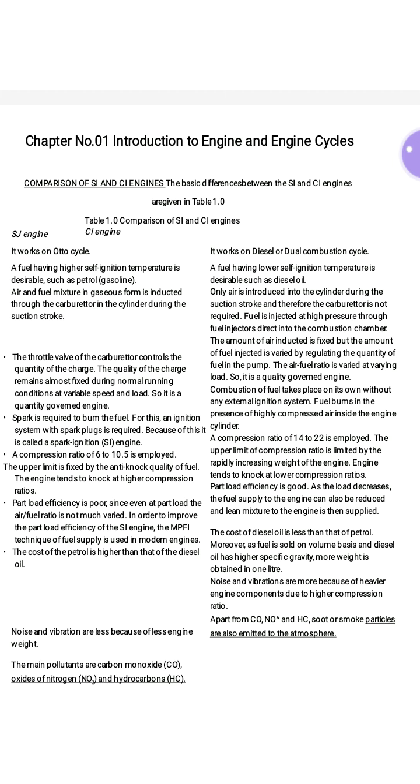Next, in an SI engine, part load efficiency is poor since even at part load the air fuel ratio is not much varied. To improve the part load efficiency of SI engines, the MPFI, that is multi-point fuel injection, technique of fuel supply is used in modern engines. In a diesel engine, part load efficiency is good compared to an SI engine.